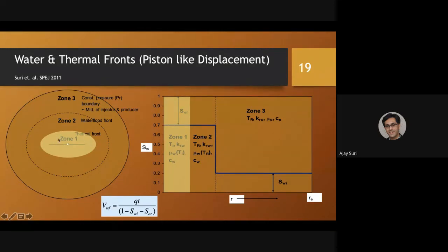But what about the pressure drop in the reservoir? That is more or less constant, but we still have to calculate it, because it may sometimes have an impact on injectivity, for example if mobility is changing or if transient effects are there. So for that, we assume a single injection well inside a reservoir, with a known average reservoir pressure at some distance. That boundary represents an average pressure, so we can solve the problem and calculate the pressure drop in these zones using Darcy's law if it's steady state.